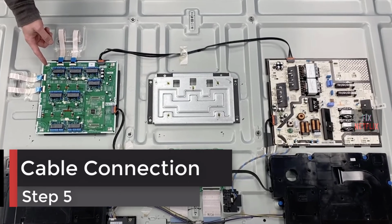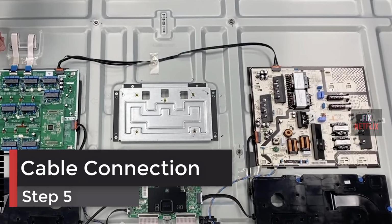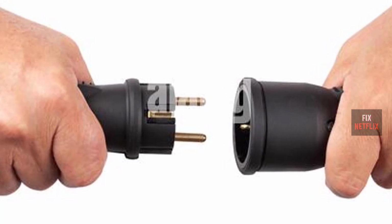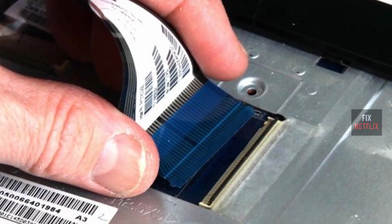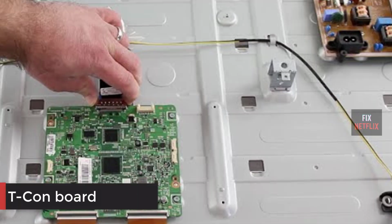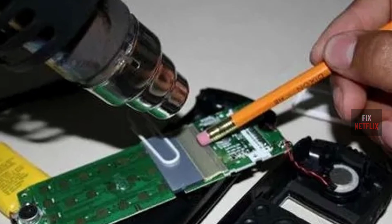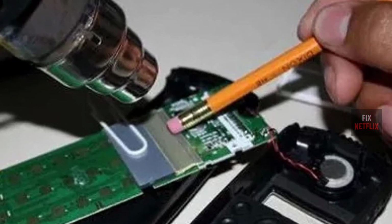Step 5. Cable connection. Even before you test the various boards, just disconnecting each cable and reconnecting it can sometimes fix the problem. Especially important in this step are the ribbon cables that run between a small board called the TCON board and the main board. You might even want to clean the contacts on the ribbon cables with a pencil eraser before reinserting them.